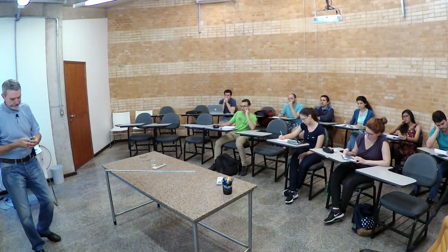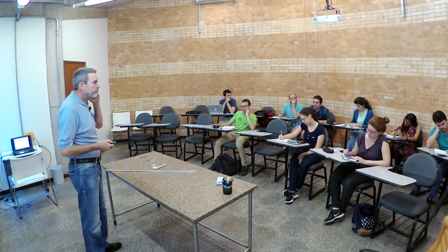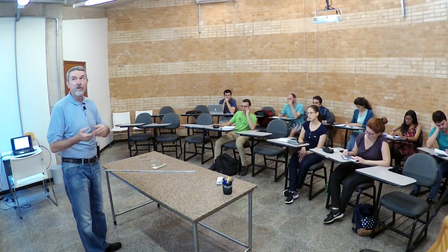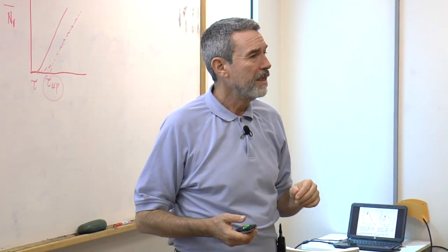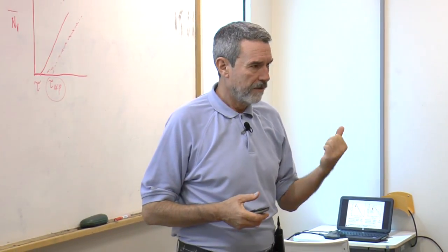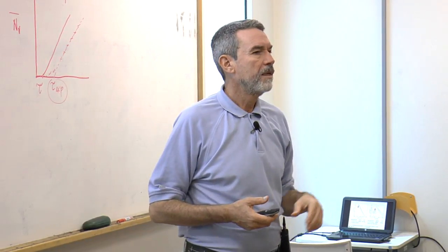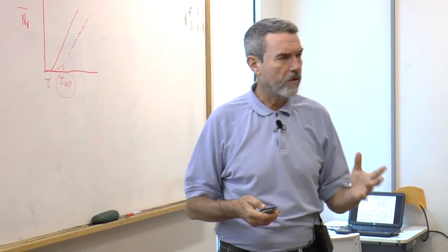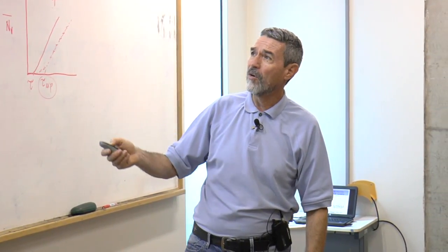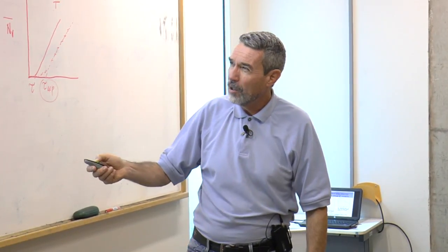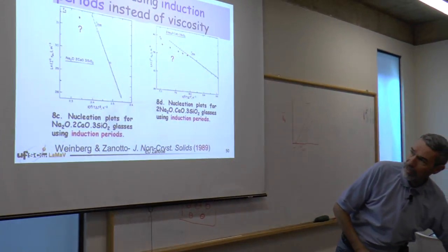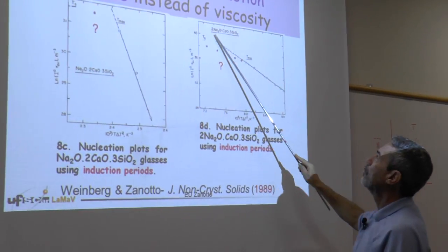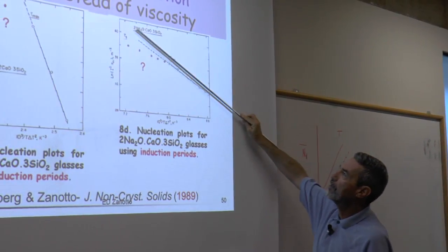induction times. Did you calculate the surface energy for this? Yes, they are about the same. The surface energy calculated in this way are about the same as the surface energy calculated using viscosity, 200 millijoules per square meter or so for lithium disilicate and for other systems. We did this for other systems, the same analysis using experimental tau. We did the analysis for several systems.